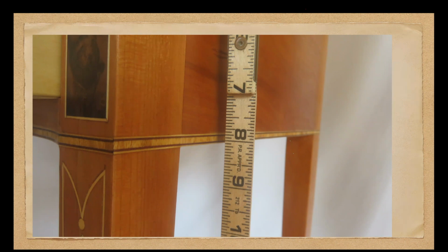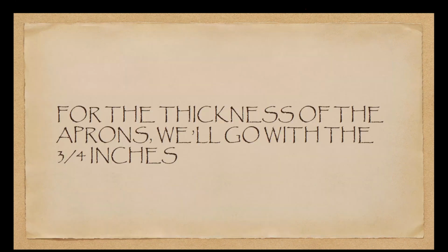In addition, if you look at the drawer side, the apron that is on this particular table is flush with the side of the leg as opposed to being inset. If you want to make it flush, that is certainly your option. But believe me, it takes a whole lot of precision to have that exactly flush and matching. Whereas if you have a small inset, then it will be a whole lot easier to construct.